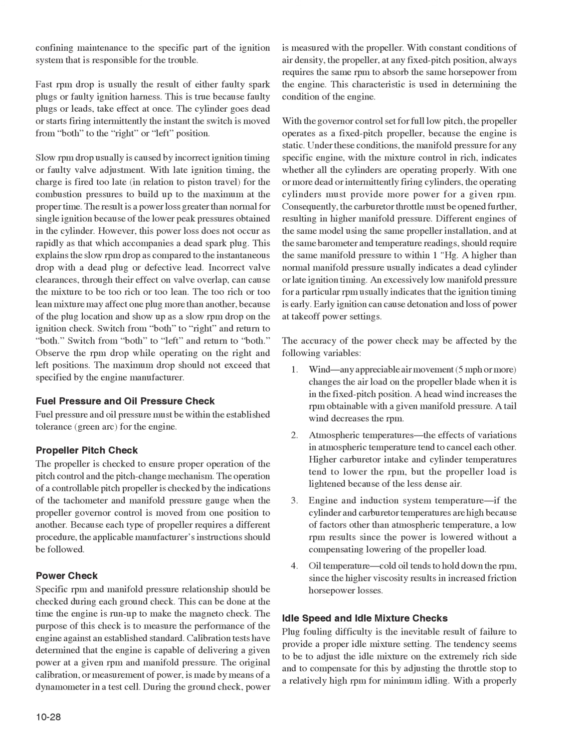A higher than normal manifold pressure usually indicates a dead cylinder or late ignition timing. An excessively low manifold pressure for a particular RPM usually indicates that the ignition timing is early. Early ignition can cause detonation and loss of power at takeoff power settings. The accuracy of the power check may be affected by the following variables.